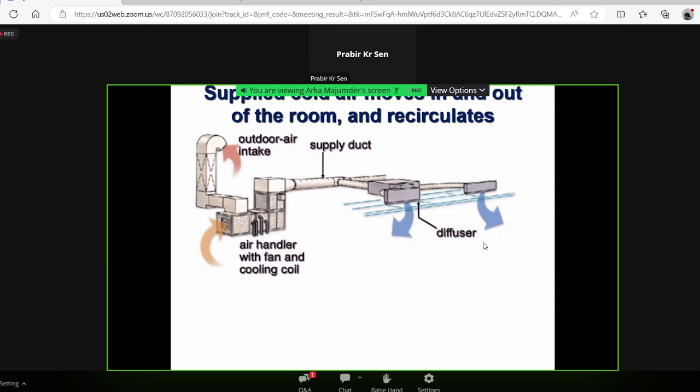Like from the bottom of the door or around the window. If somebody opens the door and goes out, air will only come out from the room. The room will remain in slight overpressure. So whenever there is an opportunity, air will only leak out from the room. The pressure inside the room will be slightly above the ambient pressure. No outside air can enter the room when you open the door or if there is a leakage source or an opening. Air will only come out.